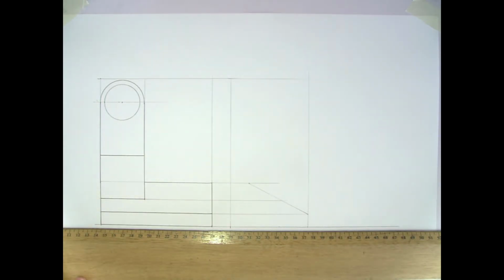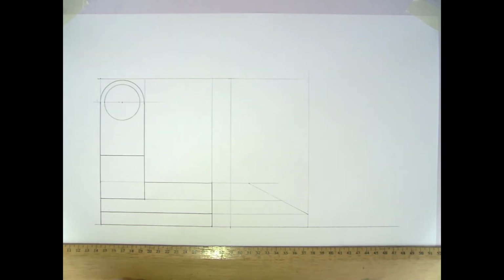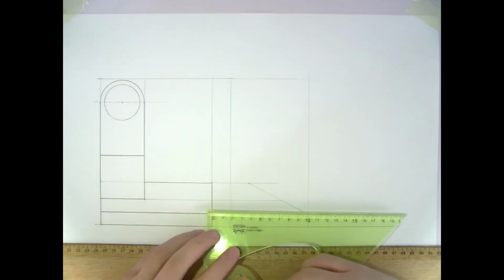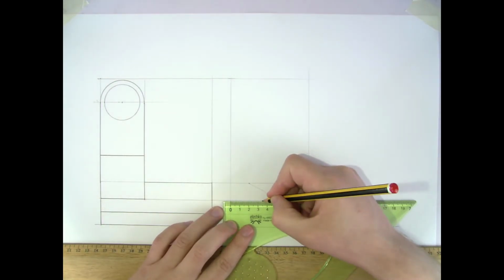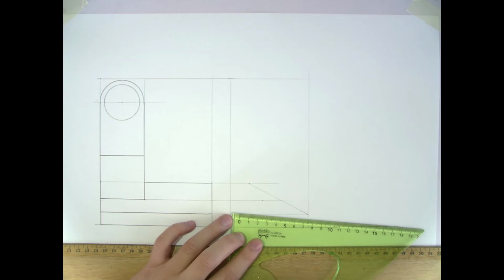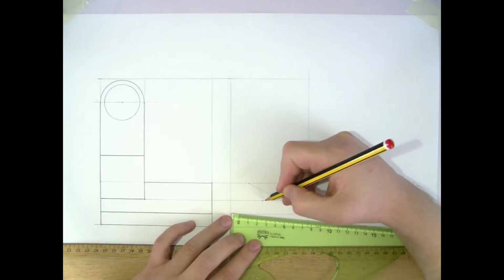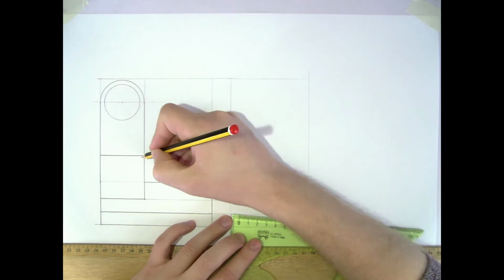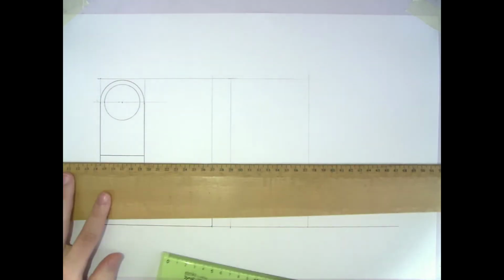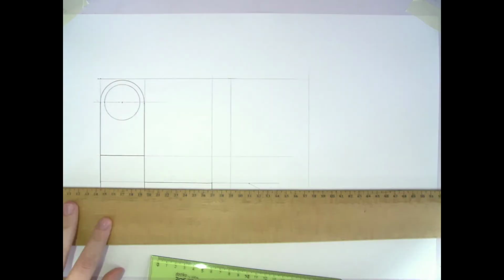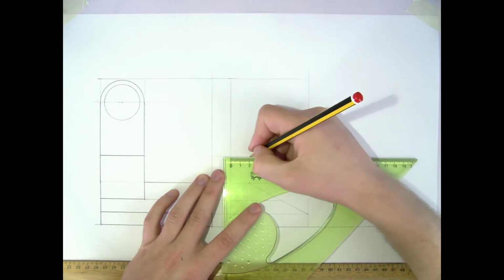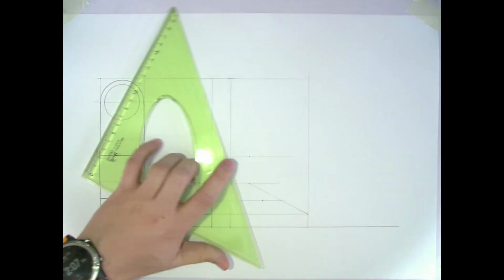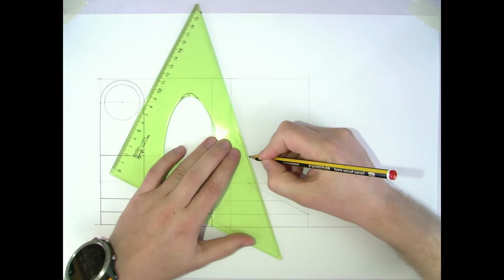That's also the bottom of our phone, and the width that we're given for the bottom of the phone is 20 plus 15, so 35. So we'll mark our 35 here. That sloping edge continues on up along here somewhere, and that's at this height. So we can take this height and mark that one across, and that comes to a distance of 20 millimeters. So I can mark this 20, and now draw a straight line between the two using the edge of my set square.